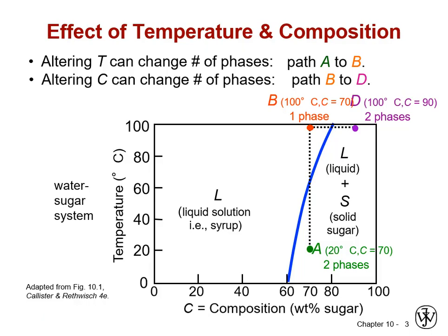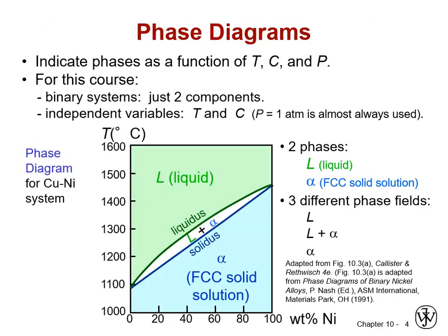So when you look at the state variables that are shown on a phase diagram, there will usually be a note, if you're looking at one generated from someone else's data, which other state variables are assumed and their values. So like I said, not knowing anything else, you can assume that anything in this class is going to be at 1 atmosphere of pressure. But if that ceases to be the case for whatever reason, you can no longer use the values coming from your phase diagram. A word of warning.